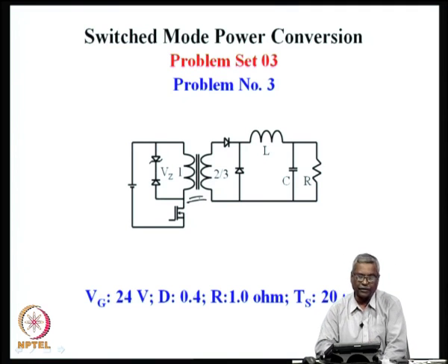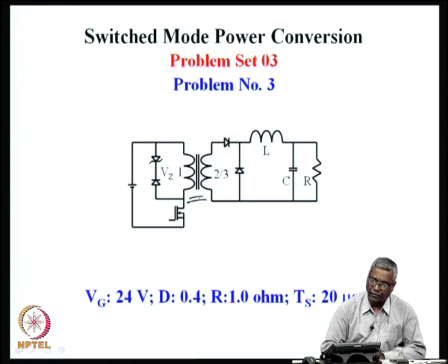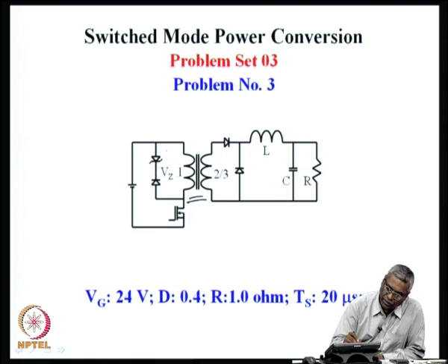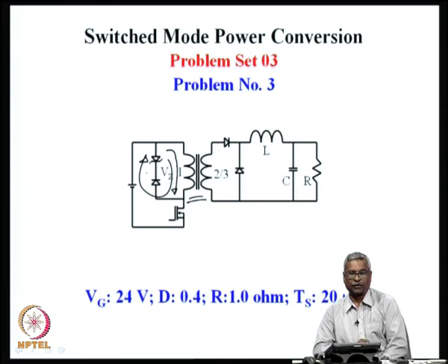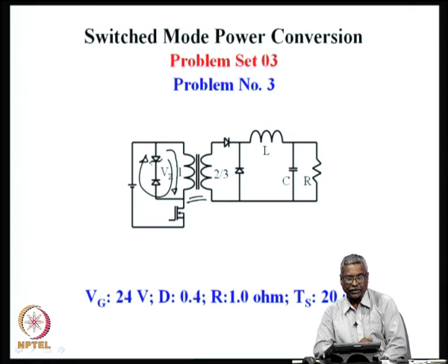This is a forward converter. We had seen how this forward converter has magnetizing current, which is built up during every on time, and then it is lost in the Zener diode during every off time. So, the magnetizing energy is lost in the diodes and the Zener diode, which is on the primary side of the